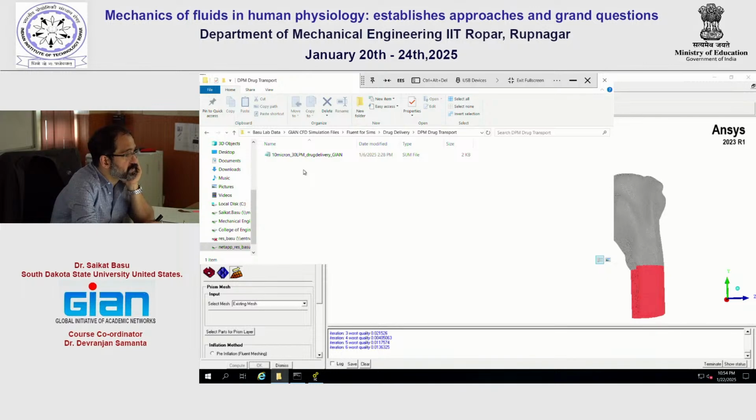Yeah. So you need to know the coordinates from where the particles are starting out. Now, in terms of the pathogen transmission one, those coordinates are the centroids of the surface elements in the mesh. On the other hand, for the conical injection, because the spray is supposed to be inserted inside the airspace, you have to actually figure out what the coordinates are from where the particles are going to be ejecting out. And they are point particles, yeah.